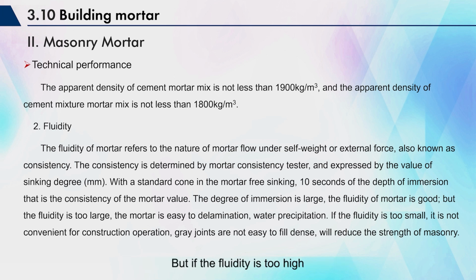But if the fluidity is too high, the mortar is prone to layering and water separation. If the fluidity is too small, it is not convenient for construction operations, and the mortar joints are not easy to fill tightly, which will reduce the strength of the masonry.